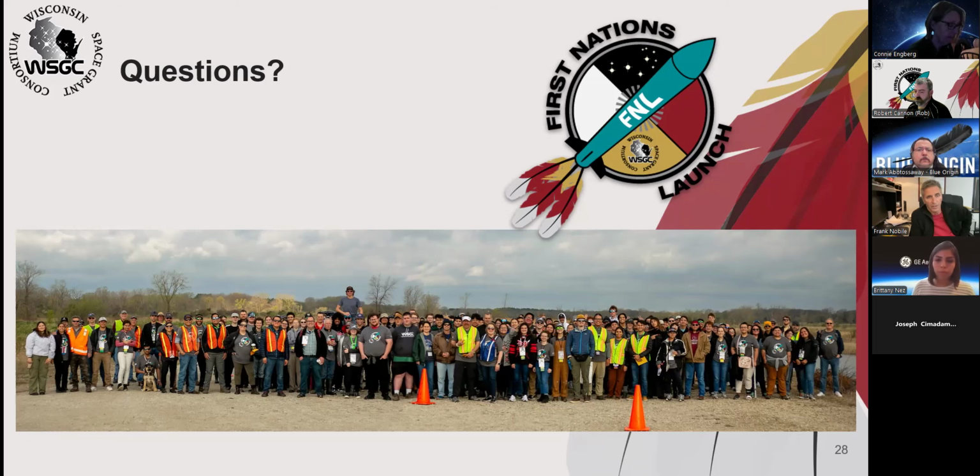Test, test, test. There's nothing worse than when you get up to the pad and you have a sensor that is not going to work. Well, you've got one sensor that doesn't work, maybe two sensors. It's going to take some time. We'll give you time at the pad. If your batteries are getting low for some reason, always have full charge batteries. We will give you the chance to turn on your power devices like 30 or 40 seconds or 1 minute before liftoff, just to make sure everything is operating properly.